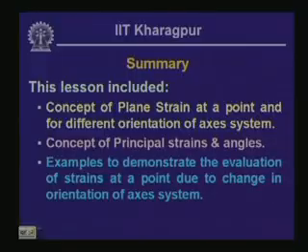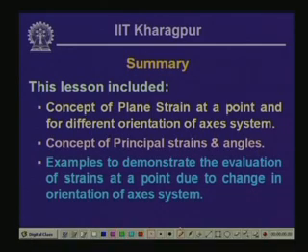So, these strains which we evaluate in other reference axis in terms of epsilon x, epsilon y, and gamma xy, we call them the transformation equations. Then there is the concept of principal strains and principal angles, as we did in case of stresses. From the strains we can compute the values of principal strains and the principal angles, which we have done here.